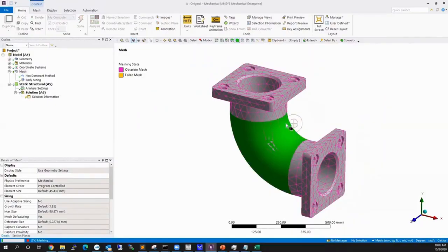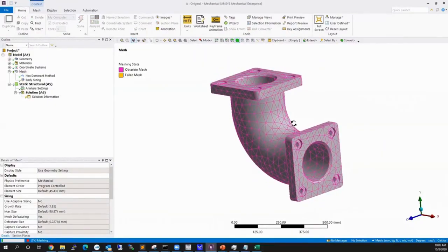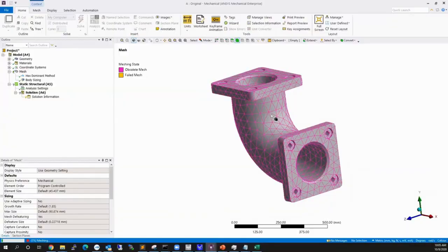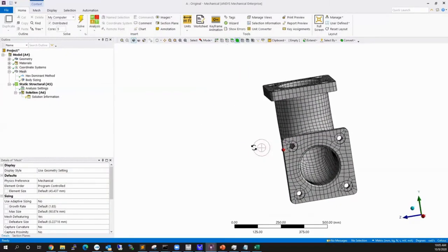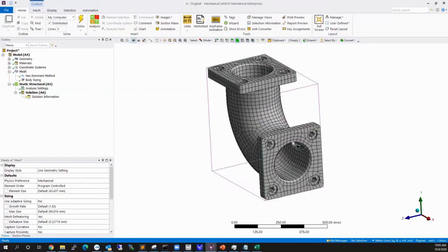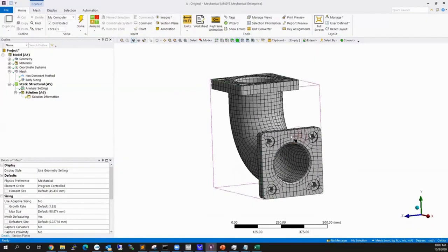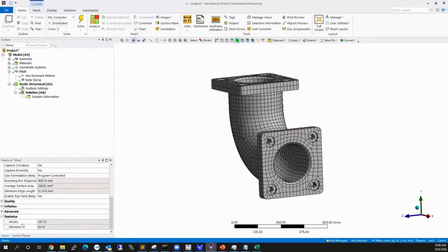Now, again, these are relatively quick methods to put on there, but they're not always as efficient as you'd like. What you'll see is that we'll have a nice hexahedral looking mesh here, but our element quality actually isn't going to be as high as we'd like. And also, you're going to see that we have about 29,000 nodes that we're going to be working with here.